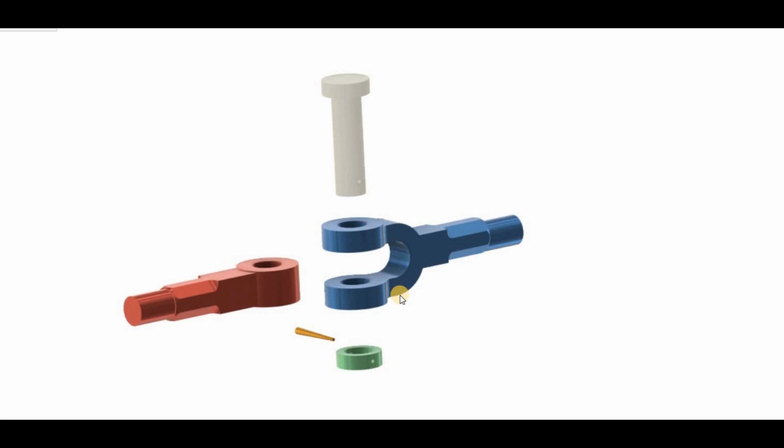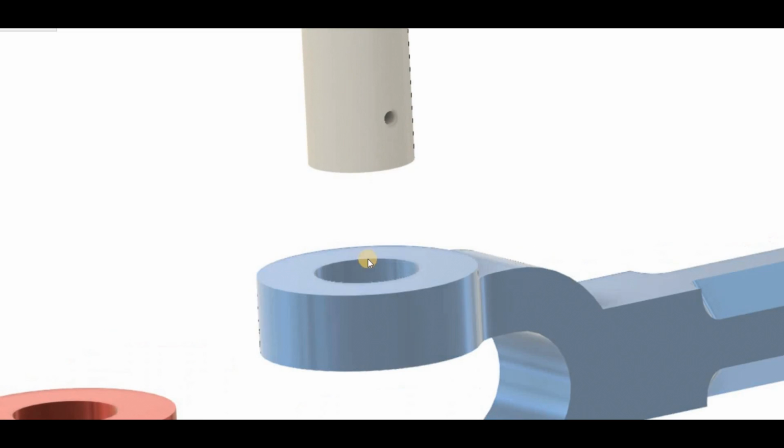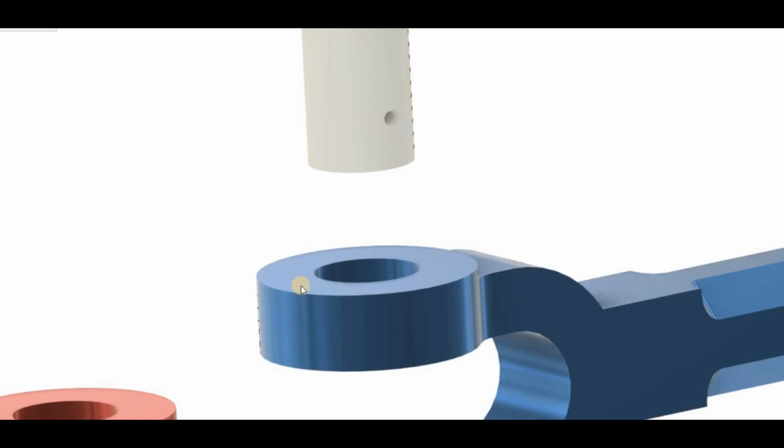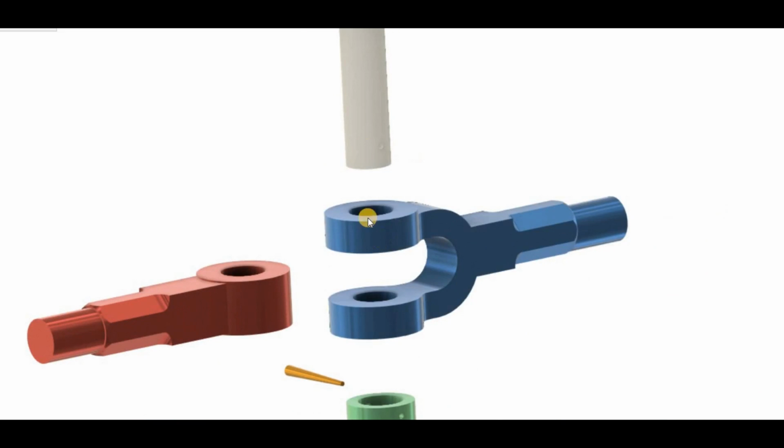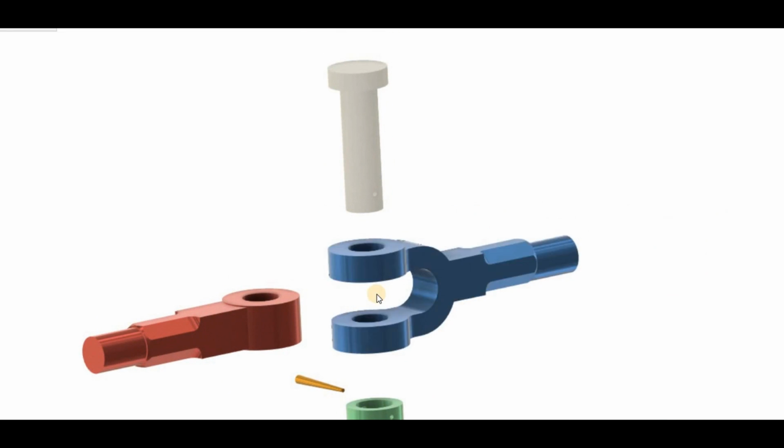This is the assembly of a knuckle joint. So let us try to understand the important features which will lead to a successful assembly of this. The first thing that we need to consider is the size of this hole or these holes. Then only this part will go inside. That is the first most important feature for giving our tolerances: size.